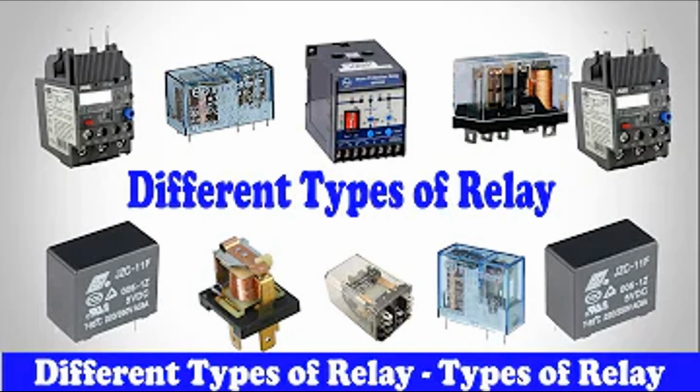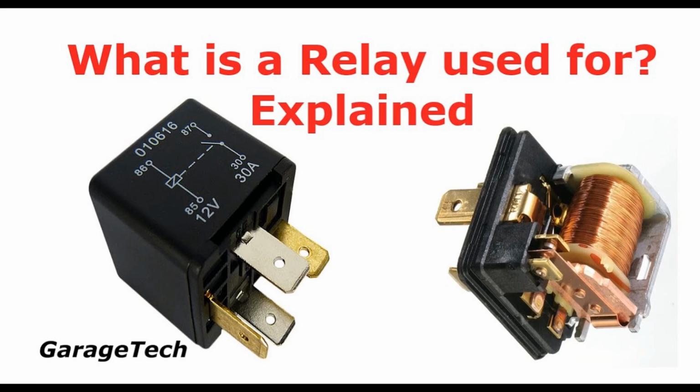Interaction with permanent magnet. The relay's permanent magnet is set up so that it either attracts or repels the magnetic field created by the coil, depending on the polarity. Contact switching. If the magnetic field from the coil aligns with or opposes the field of the permanent magnet, it causes the armature to move and switch the contacts. Polarity sensitivity. The armature only moves if the current polarity matches the relay's specific requirements.